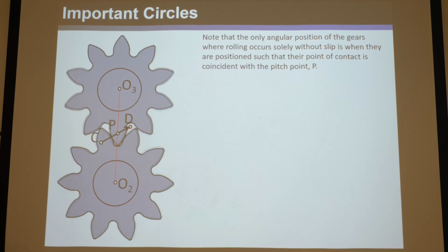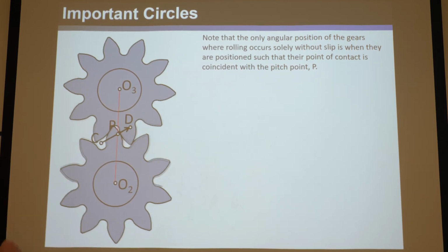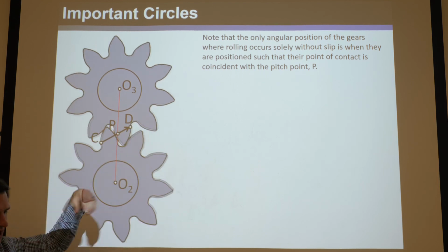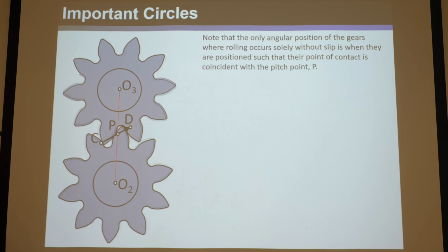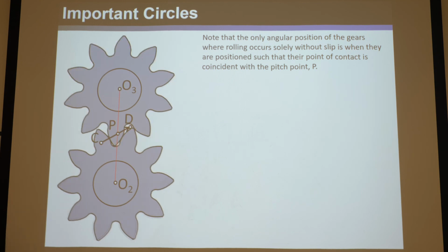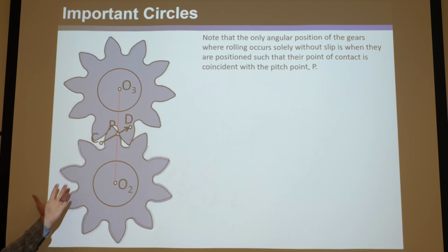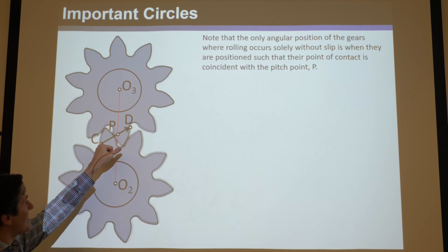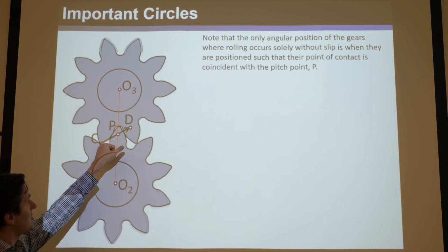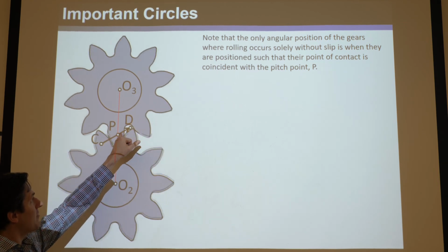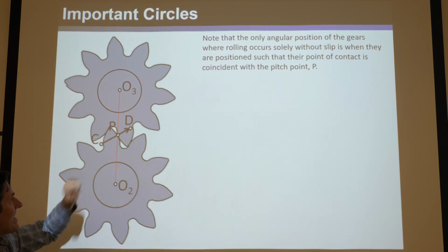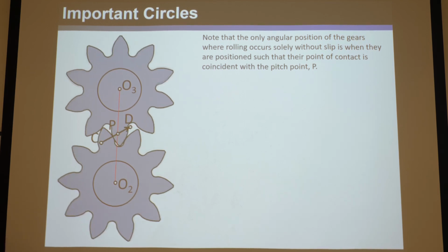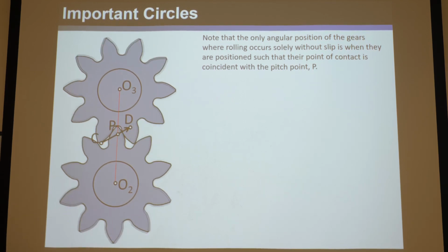Okay, but getting to this point, there's a very roundabout way to say, in reality, even though we always model gears as a J1 rolling contact only, the truth is, as their teeth go through the mesh, where they touch, they're actually sliding and rolling along each other from C to P, and then from P to D. But at P proper, right at that point, that's the only point where they really are pure rolling.